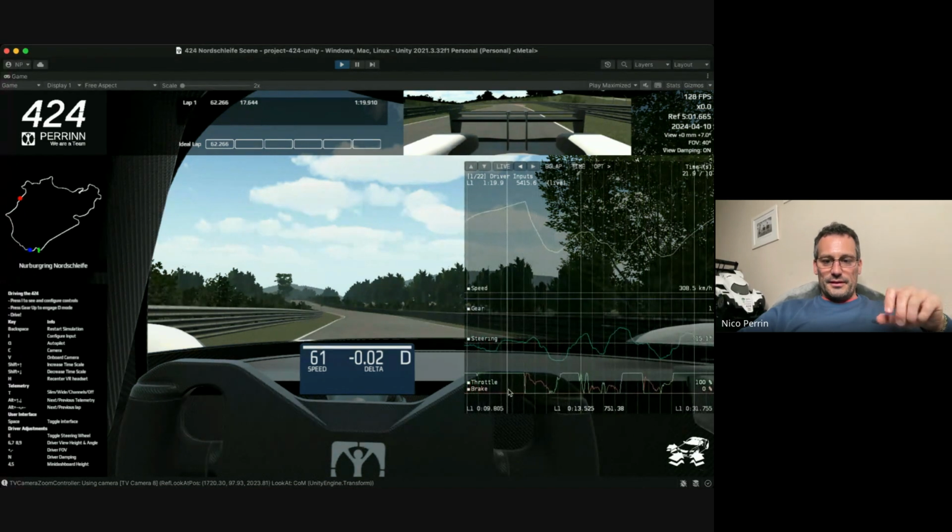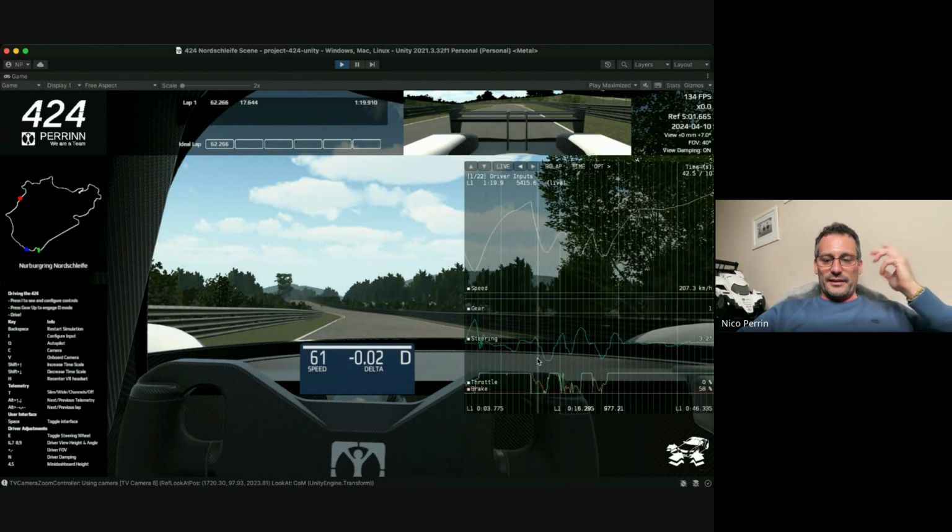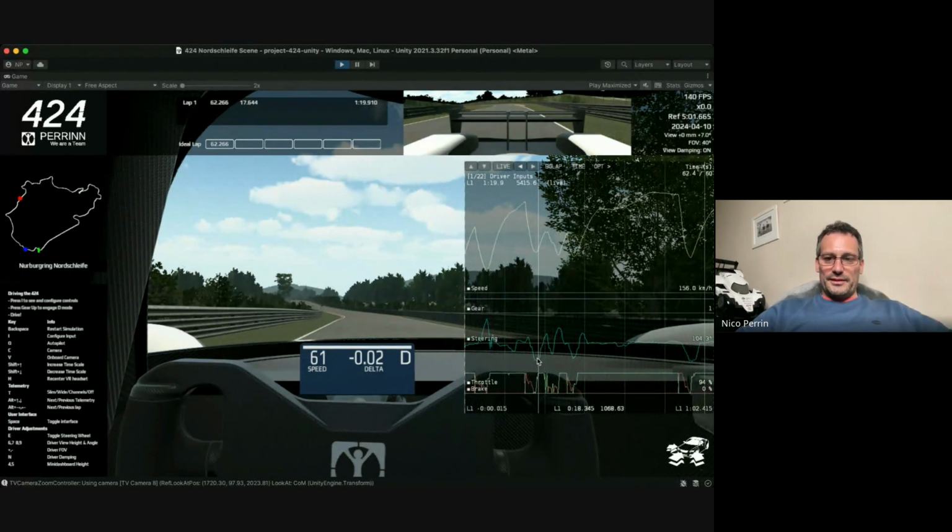Typically the brake pressure is always of that sort of shape. Very hard braking, obviously at high speeds, when downforce is on the car. And as the speed decreases, we have to release the brakes because there's less loading and we're starting to enter the corner as the steer angle increases. Okay, that doesn't tell you much, but this is page 1.